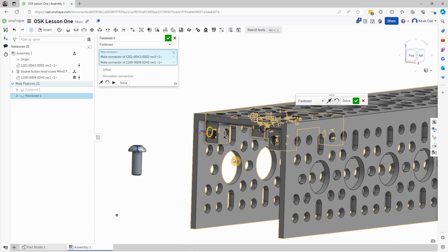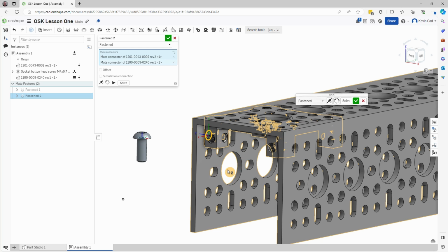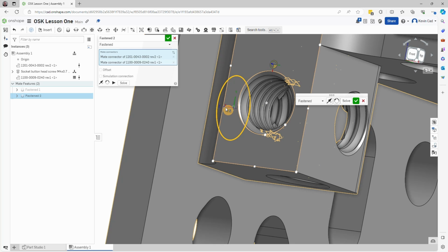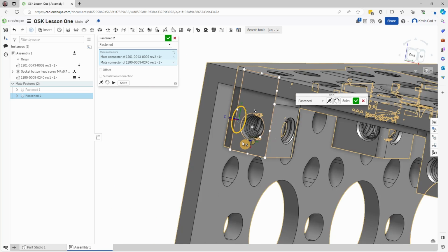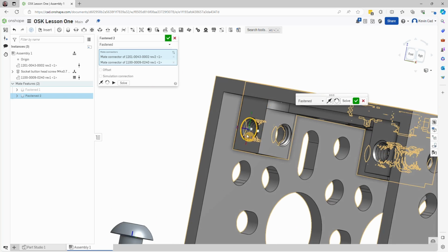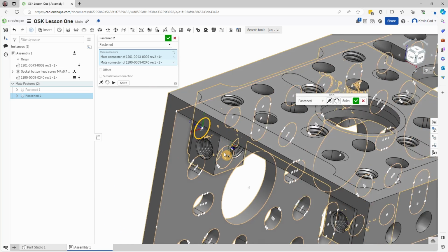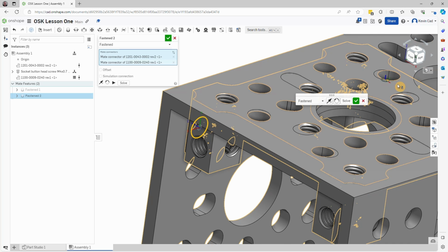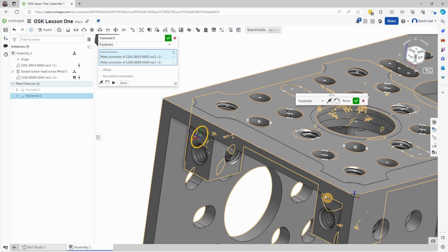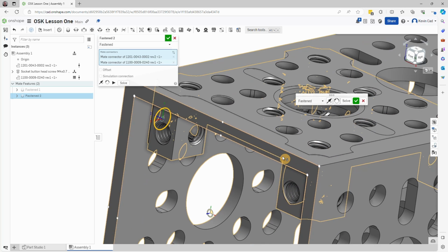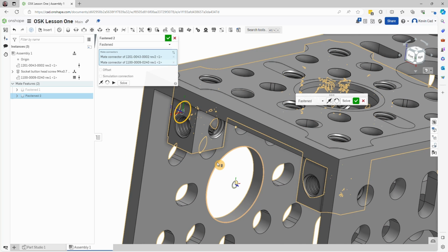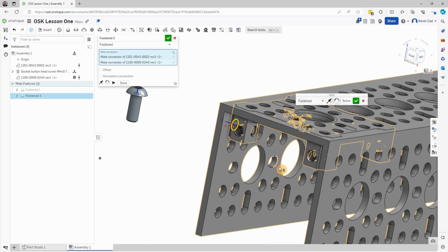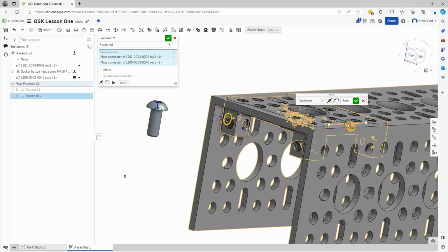The other thing I'm going to point out is I may have gotten this backwards. So let's see what happens. The Z-axis has aligned fine. I'm okay with that. But the orientation of the rest of the part doesn't seem right, and you can see it sort of embedded itself. This is a thing that happens a lot in CAD when you go to assemble things. It doesn't know what orientation you actually wanted, and it can occupy the same space at the same time. So I would actually like to reorient this part.